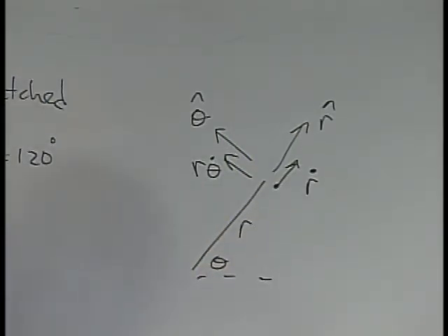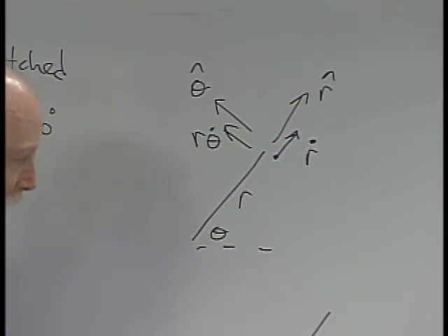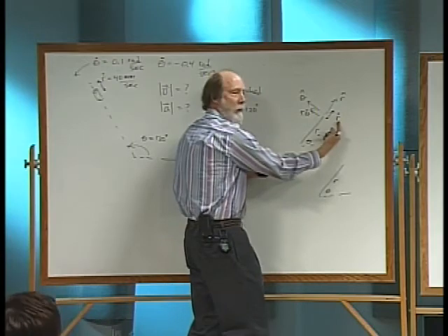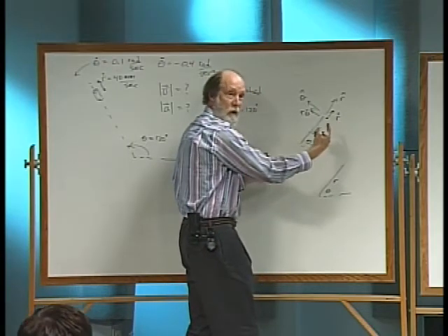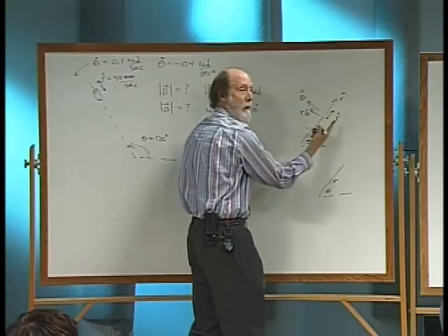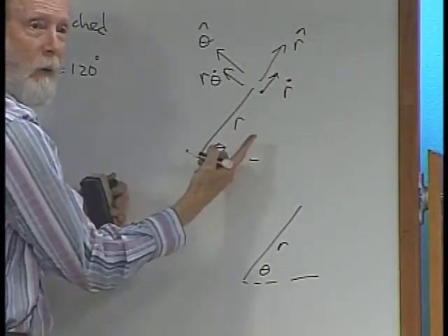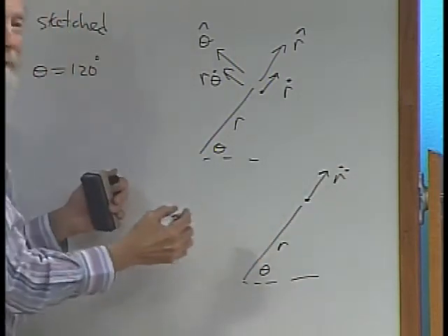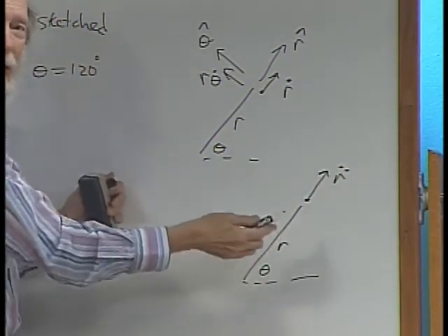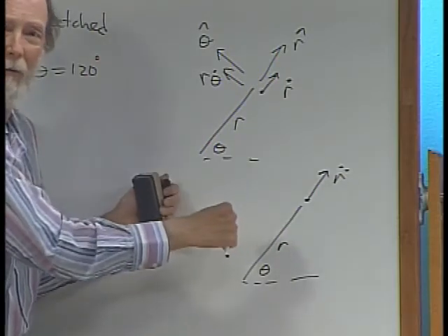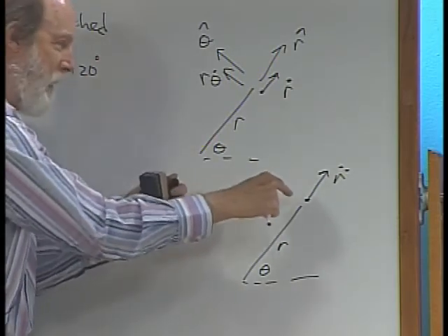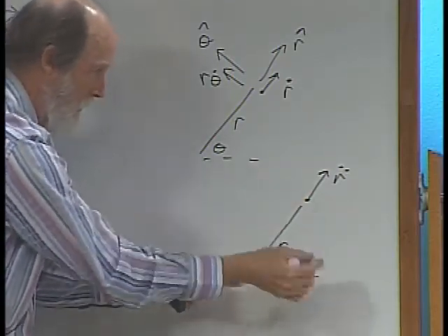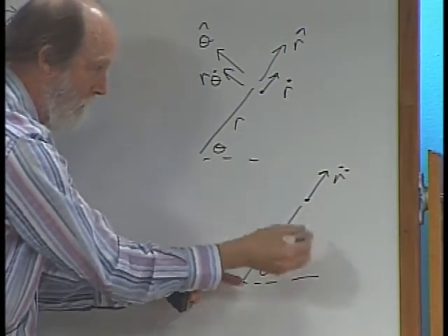Now, if you're going to do the acceleration and try to remember it, then you want to think, okay, this radial telescoping term could be changing with time, so there could be a telescoping effect, accelerating it outward or inward. So you should expect that. And if it's on some curved path, you know there also has to be a term directed back towards the center of curvature, or it's a pseudo-normal term because the path may not be directly circular or perpendicular to this arm here.